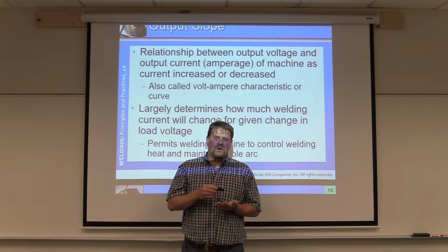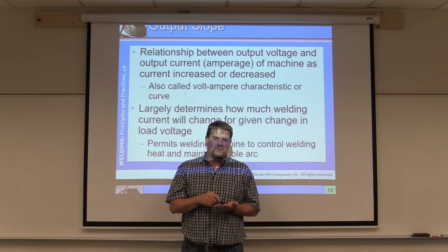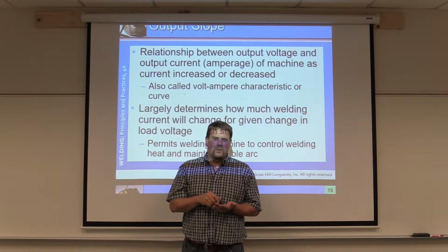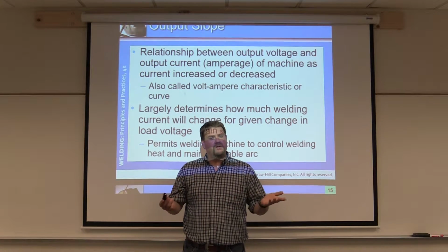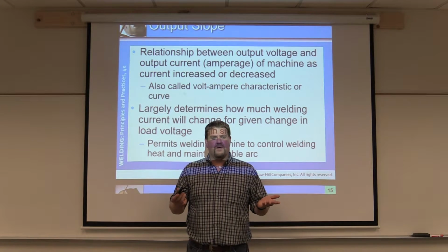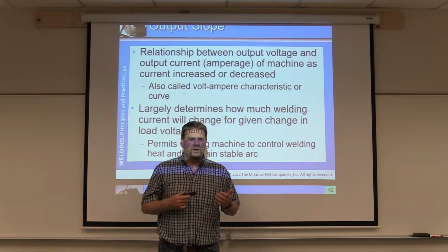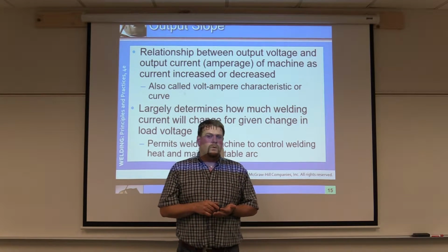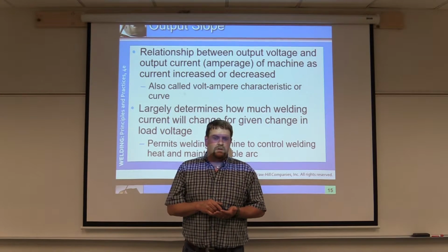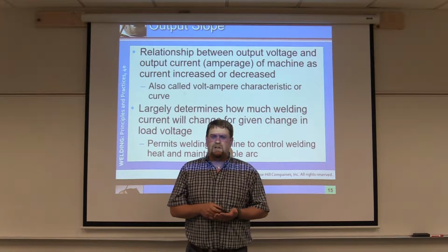heat. I mean, we're already starting out the weld puddles at roughly as high as 9,000 degrees. Melting point of steel is roughly 2,800, okay, 2780 to 90 depending on carbon content and so forth. However, we know we're above 2,800 degrees, so we're somewhere in that 3,000 to 9,000 degree range.